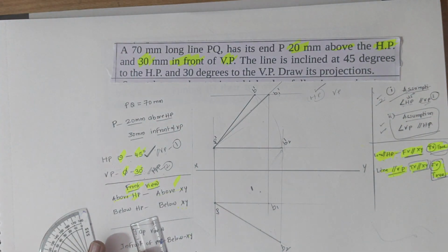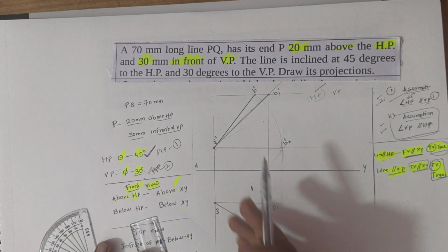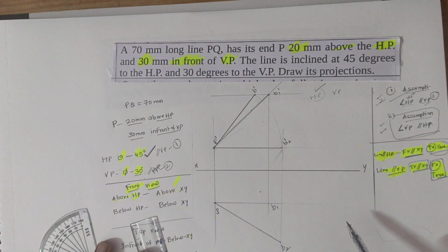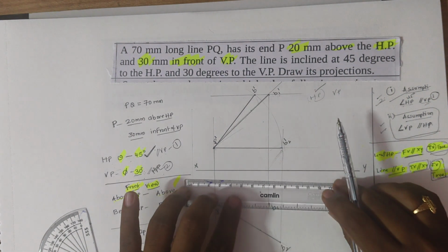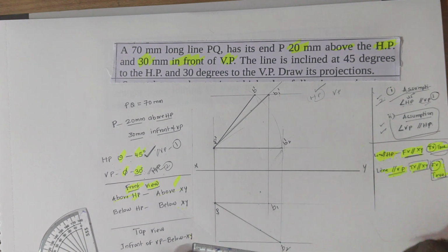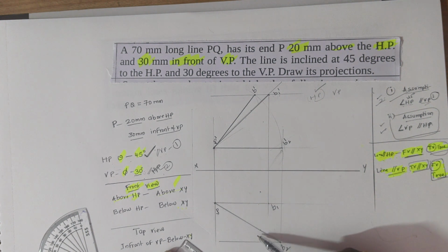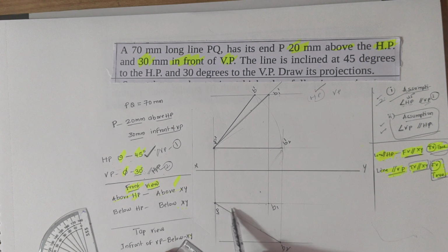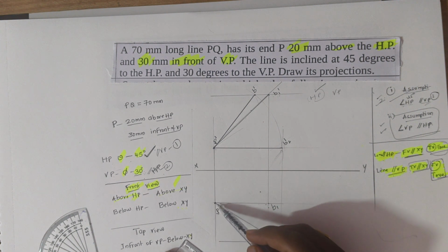Similarly, there are two top views based on the assumptions, not the final one. The final top view is going to be at the same height of b2, where the inclined top view is, and the final top view length is equal to the top view length from the first assumption, the parallel top view.